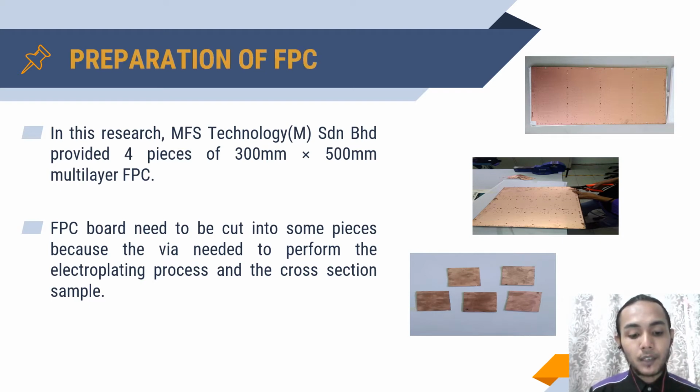Before cutting the FPC, define the via of the FPC first. Then, measure the FPC area that needs to be cut. The FPC via was cut using a cutter or a better quality cutter blade, since it is copper, a cheap cutter will become dull very fast.